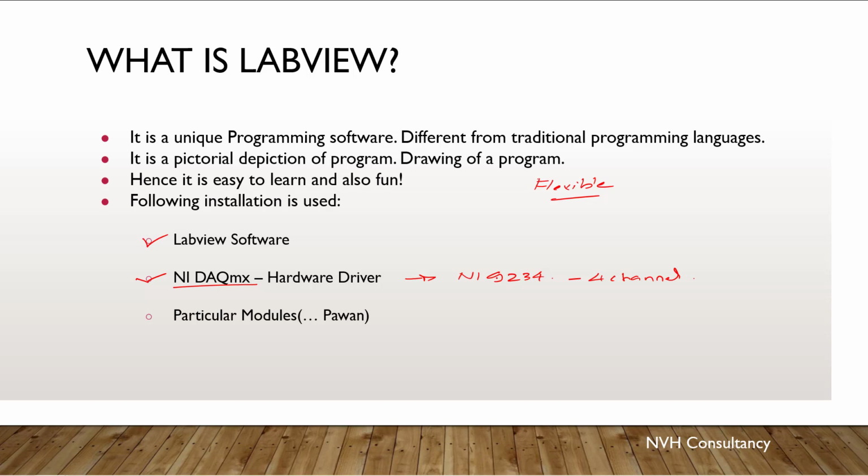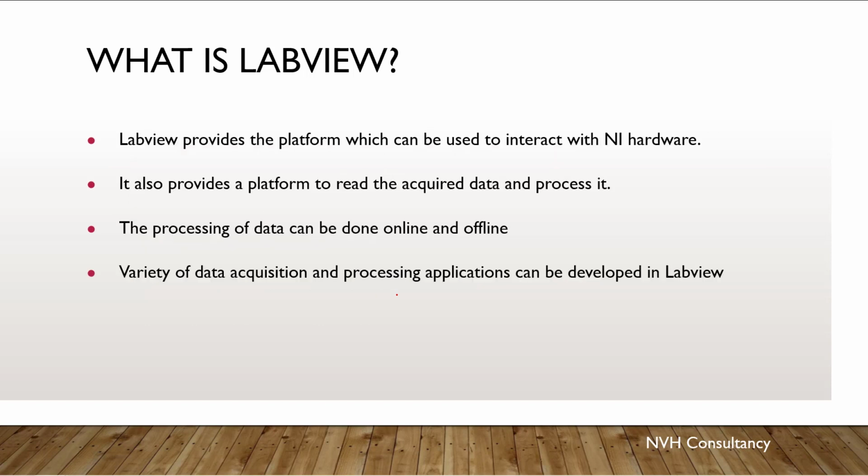Once this data is collected through the NI DAQmx, then the role of the LabVIEW software begins. You can get the data through various formats. Today we are going to look at the TDMS format, which is kind of a proprietary format of LabVIEW, and how that format can be used further to process that data. So all those things in particular.